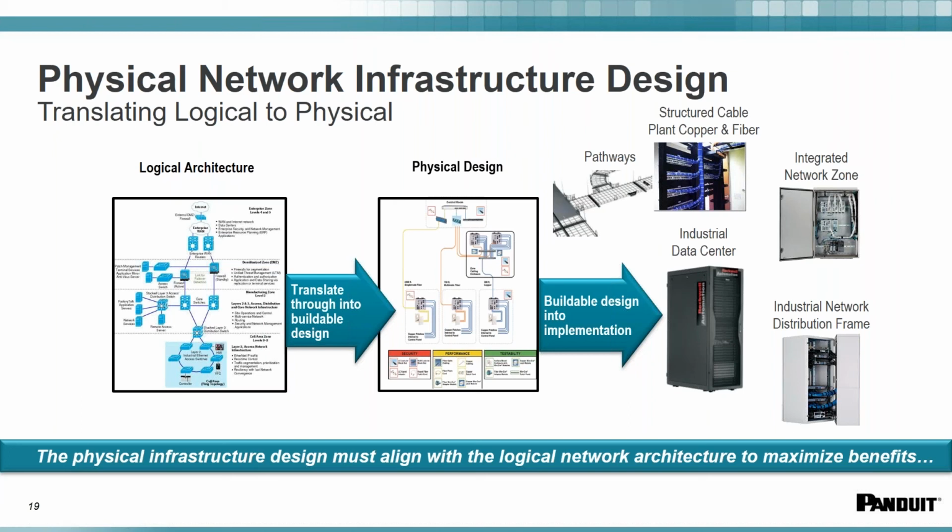then you will start determining, do I run a fiber between those two devices, or do I run copper? Is the distance between them over a certain limitation where communication cannot be secured, and fiber isn't the right answer? What type of copper has to be put in? What type of cabinet do I have to choose? Do I have to choose stainless steel, or do I use fiber type of product, or simply carbon?